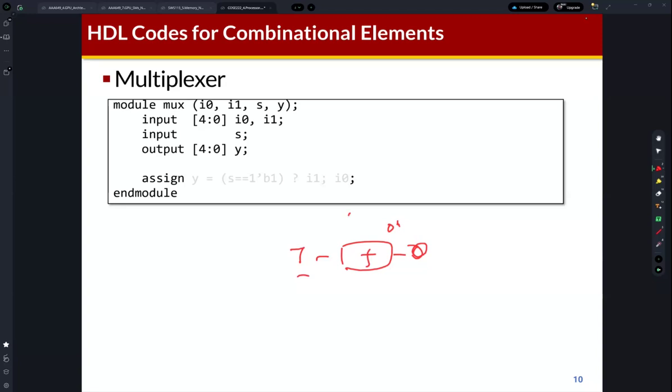But this delta t is different for different logic, obviously, right? Because we need to build the combinational logic using digital circuits, and the delay is different. The delay can also differ by environment, such as temperature, the process, and some other factors. So actually, this delta t can change.